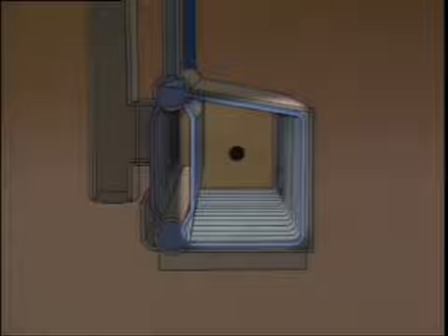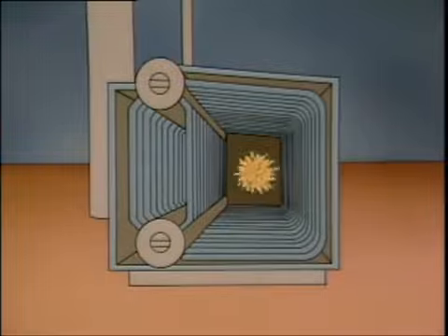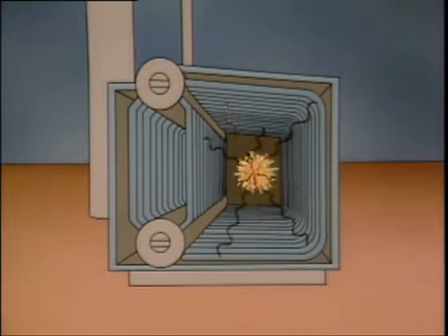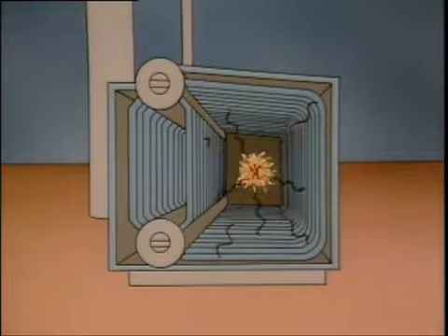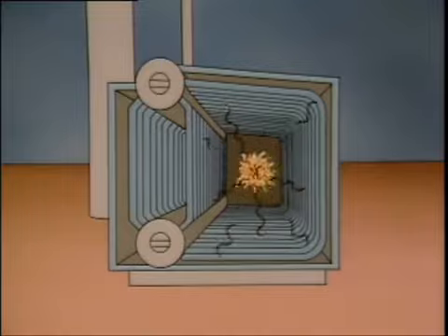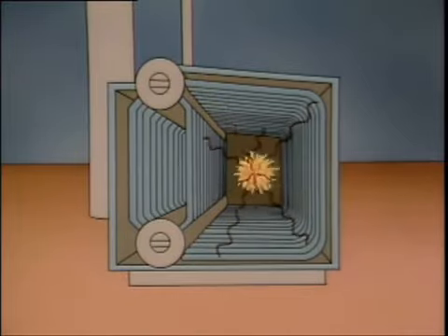The tubes form a wall around the combustion area. This is the area where heat is generated. When fuel burns in a boiler, radiant energy in the form of electromagnetic waves is produced. These waves travel through the combustion area. The waves in a direct line of sight with the tubes make contact with the outer tube surfaces, and the tubes absorb heat. This is radiant heat transfer.